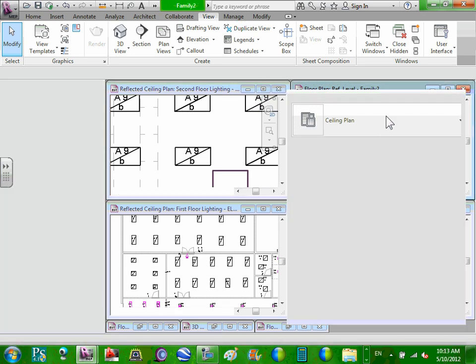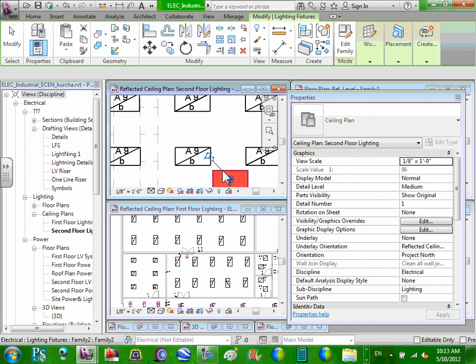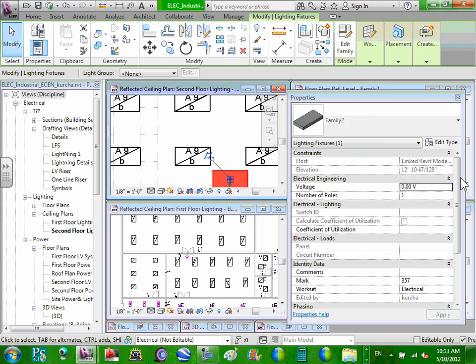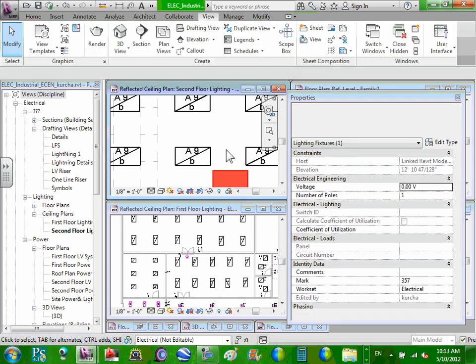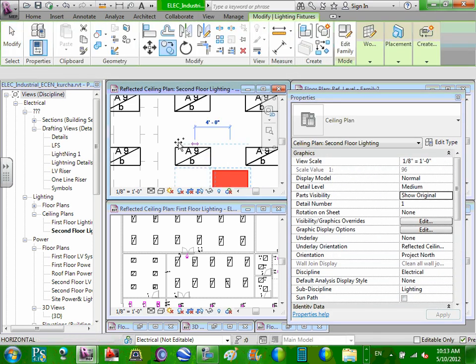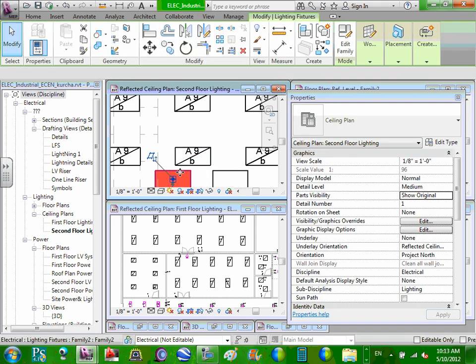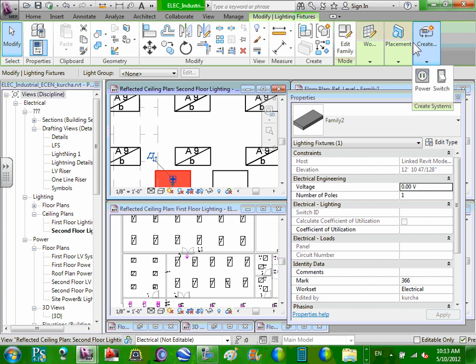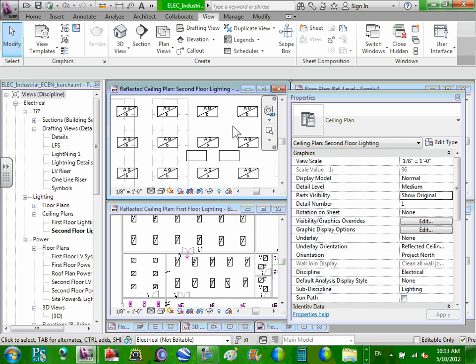Click on it one more time, please. The same one that you did, and go to properties. So now if I change each one of them individually, they can be different. Yeah. If I copy this one over here, I can make one of them 277 if I want to. That doesn't happen a whole ton with light fixtures. The junction box is a great example.